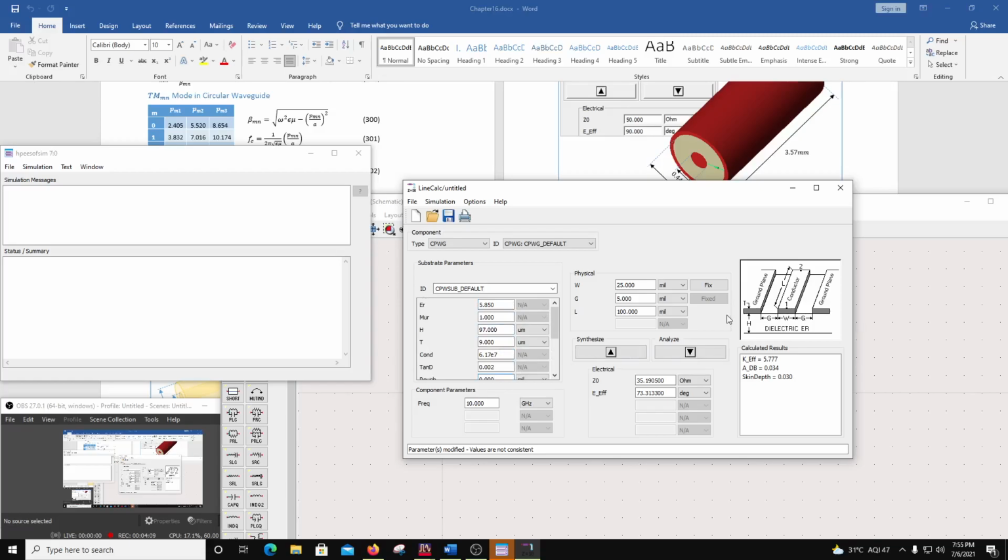But now I have an independent control of the width of the line. In case of microstrip, if it is a lossless microstrip, it is the square root of L over C which decides the characteristic impedance of 50. If you make the line wider, that's going to reduce the L and increase the C. That means the characteristic impedance of the line will go down if you make the microstrip line wider. If you make it narrower, then L is going to increase and C is going to decrease, which makes a higher impedance line. That's basically what happens with microstrip line.